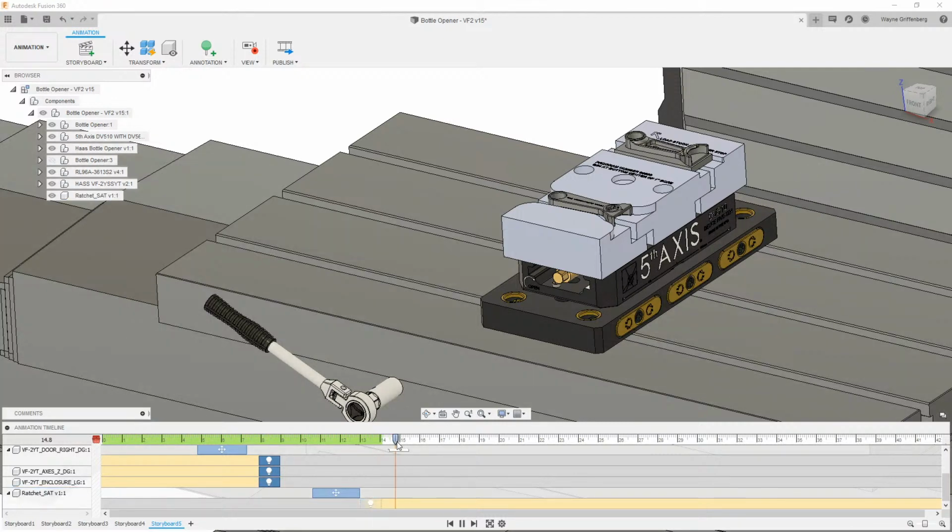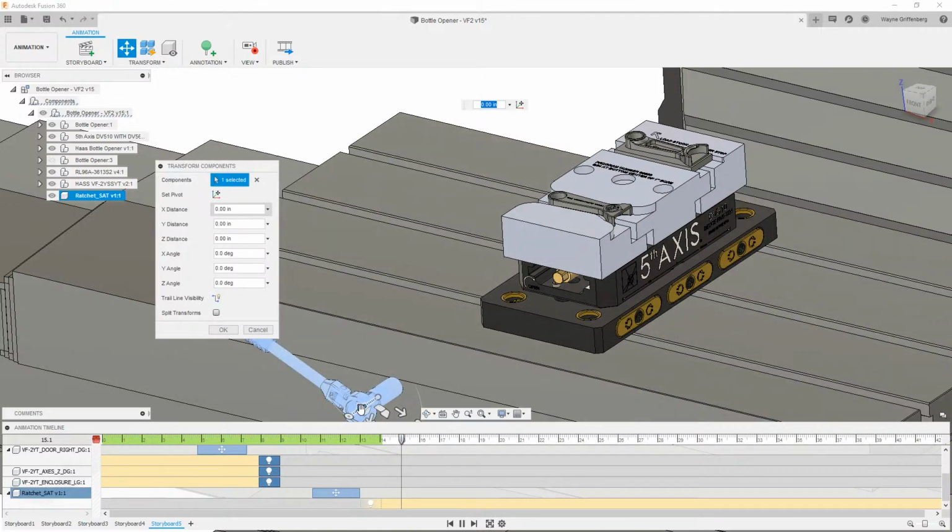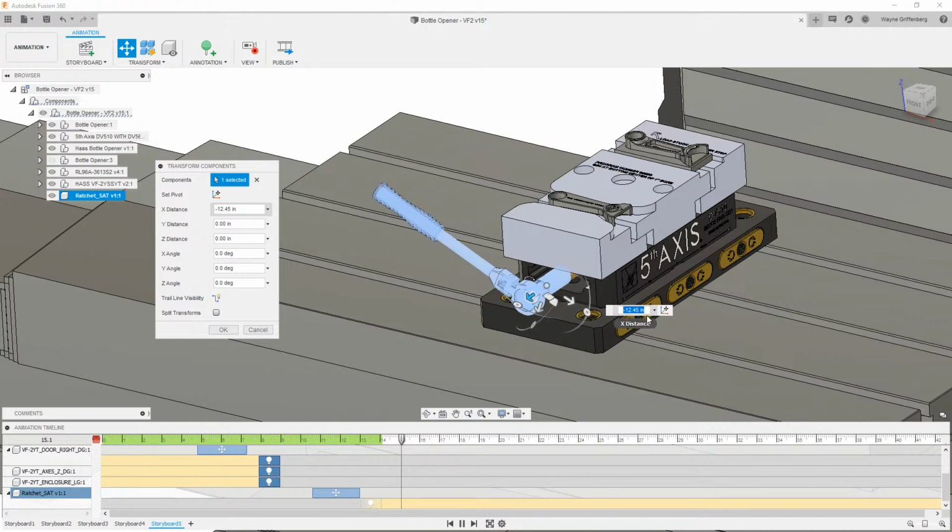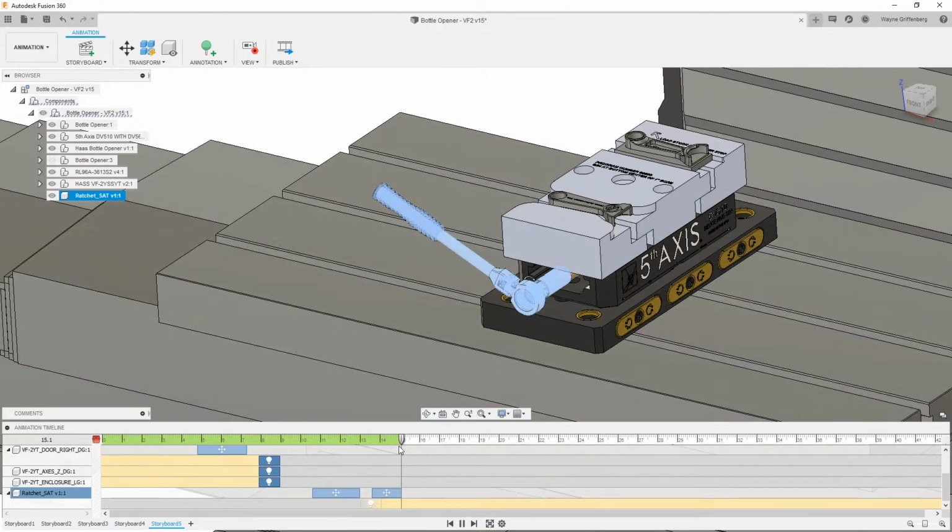And now for another second, I want to move it into position, right? So I'm going to select our move. We're going to drag this up, and I'm just going to eyeball it. If you know exactly what that distance was that we dragged it, we could just put that back in there, right? So let's go, and now that's what I'm looking for, the wrench to move in position. And now I want to rotate it, let's say, 150 degrees to the right, to go positive, right?